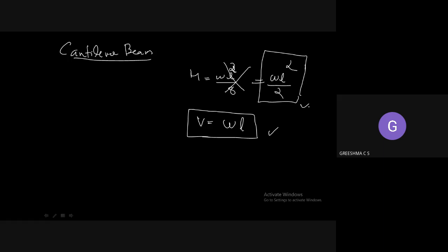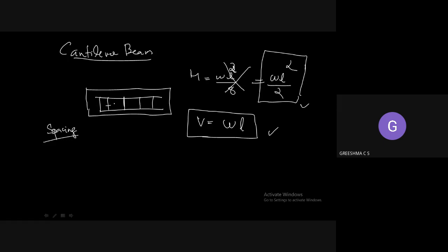So we were doing the spacing, the spacing of the stirrups in the cantilever beam, and the stirrups we have provided as reinforcement like this. How much spacing should be given to these stirrups? We had three criteria. First, we find the equation as per IS 456, but that did not work. Again we find the minimum spacing as per IS 456. That also didn't work out.